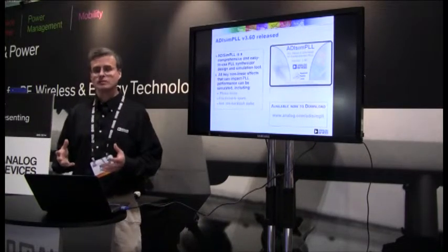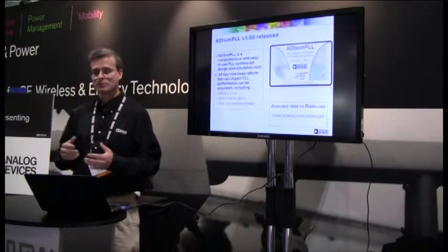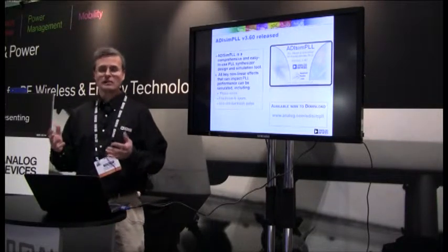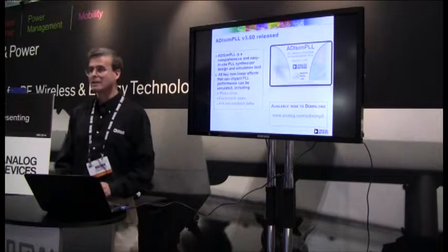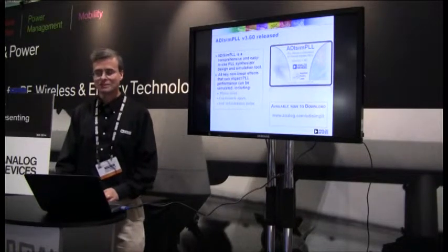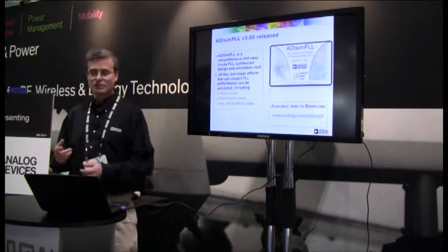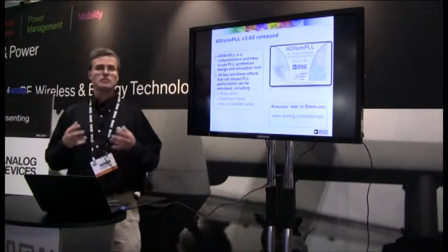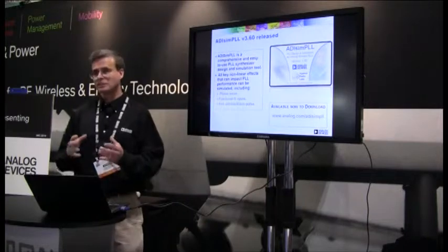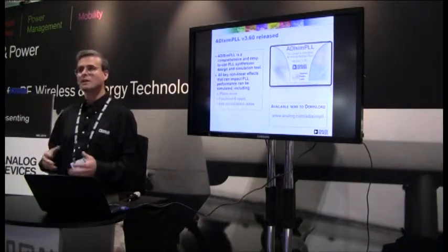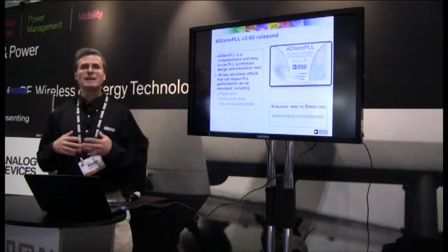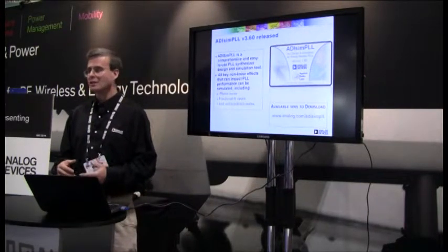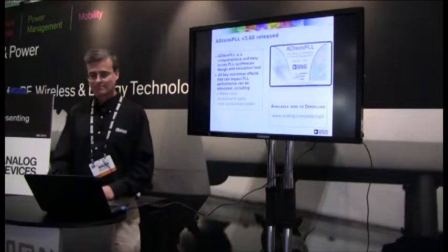What you can do with it is get the performance on all the nonlinear effects that can impact PLL performance, including phase noise, fractional-N spurs, anti-backlash pulse, all of those key parameters that you consider when you're designing a system using a PLL. We allow you to simulate those very accurately using the program ADI Sim PLL.